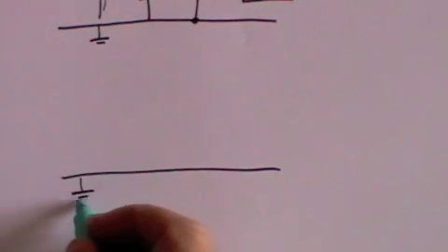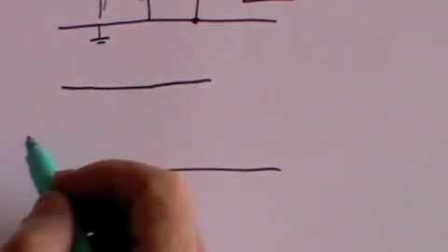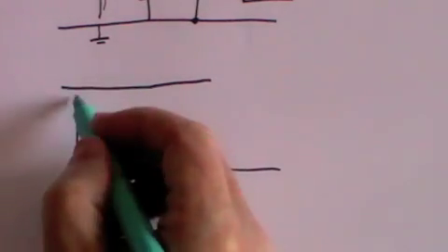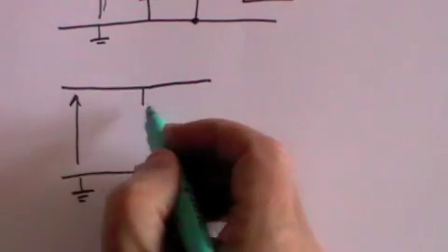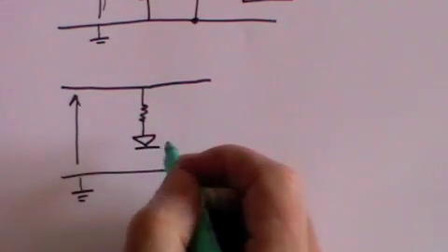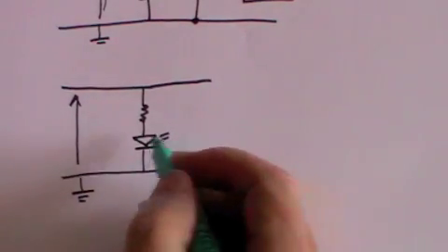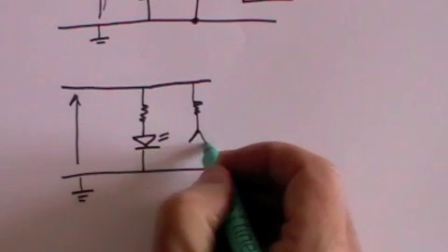So let's just consider a simple way in which they could be used. Here is the earth. Here is the operational amplifier output, which has come from the sensing device and the operational amplifier this side. And this is the voltage, which may be positive, it may be negative. How do we know which? Well, we might have, say, a resistance and then a light emitting diode which emits, say, red light if that is working. And then here's another resistance here with a diode going the other way,